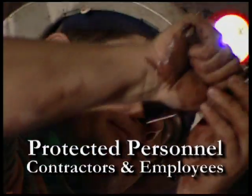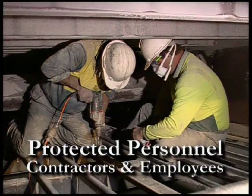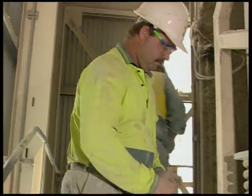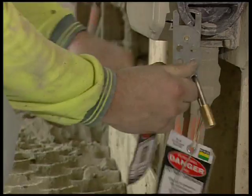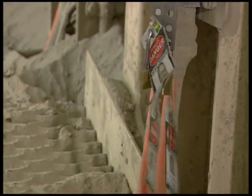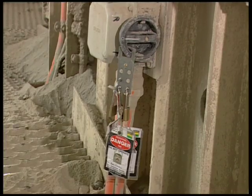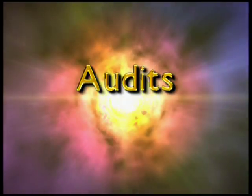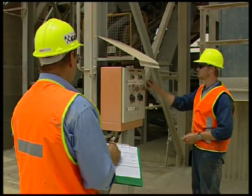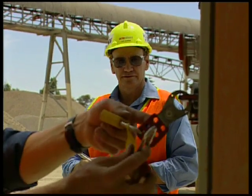Before employees and contractors start work on isolated plant, they must be trained in the site's lockout isolation procedure. Employees and contractors working on isolated plant must attach their personal locks at the required points for personal protection. An authorised employee should perform a periodic review of the lockout isolation procedure at intervals to be confident that the isolation practices comply with site requirements.